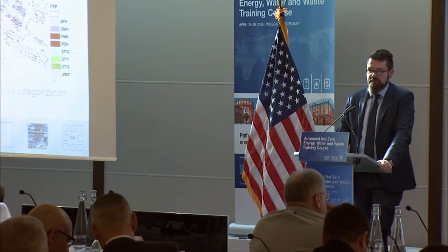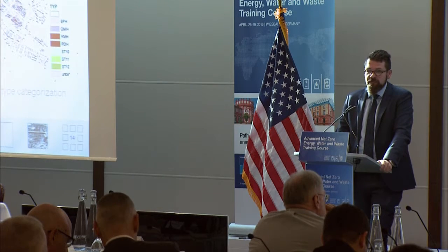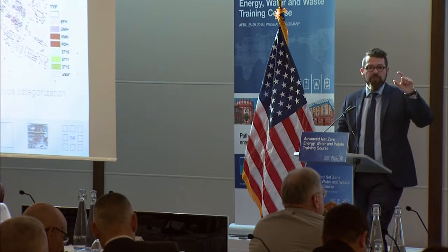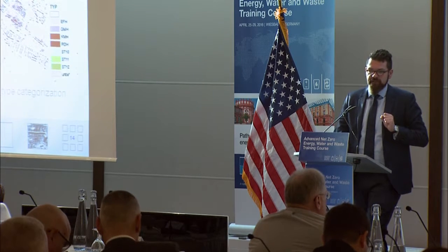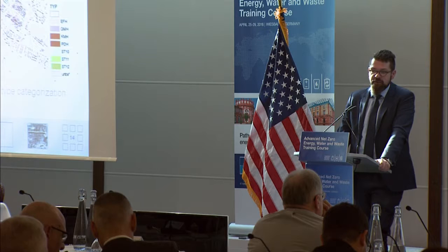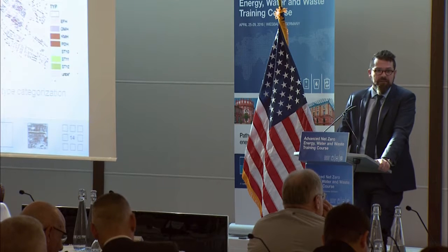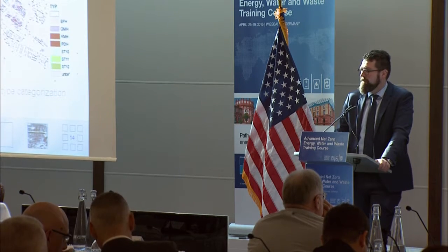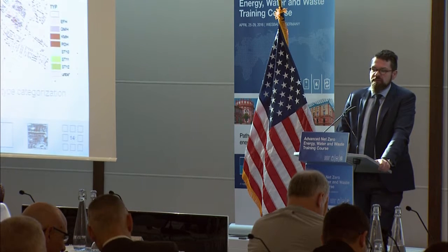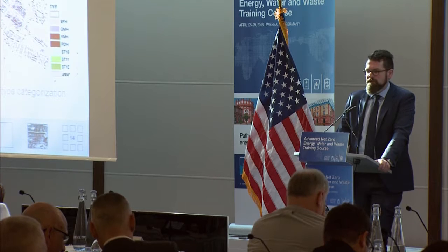What you should do is analyze the existing building stock, calculate the heat loads, as I explained a little bit earlier, and calculate the annual energy demand, so the peaks and the lowest points of each building, the duration curve, and then analyze the building utilization, occupation, and if possible the building physics. If you have an army installation, it should be quite easy. It's a little bit more difficult if you look at a large city like Copenhagen, where you miss a lot of information on those buildings. And then you should evaluate the option of connecting those buildings to a central heating or central cooling system.